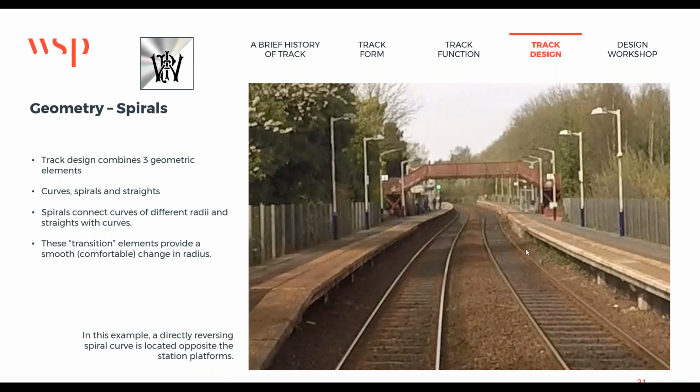And what that will give you is perhaps, and it's not a guaranteed thing, a different stiffness and maybe a different top quality in this part of the platform. These sections are typically small, they're platform extensions that have been done like that, but there may be other areas where you've got a rock cutting and the depth of the rock cutting is constraining the ballast and not allowing enough room to move sideways, and it becomes a little bit stiffer in there. I don't know if it would affect the track that much, but there will be a measurable difference in stiffness.